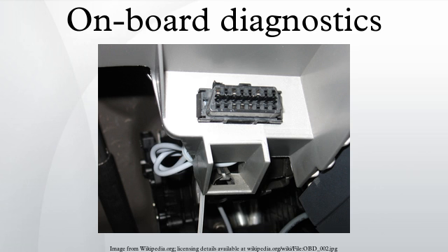Mode $0A lists emission-related permanent diagnostic trouble codes stored. As per CARB, any diagnostic trouble code that is commanding MIL on and stored into non-volatile memory shall be logged as a permanent fault code.